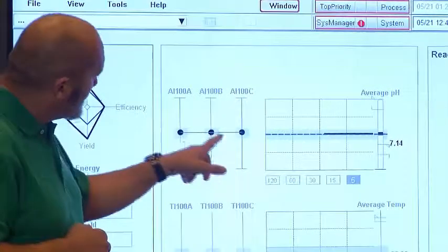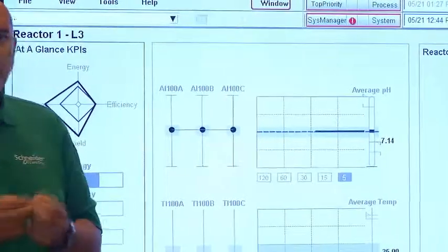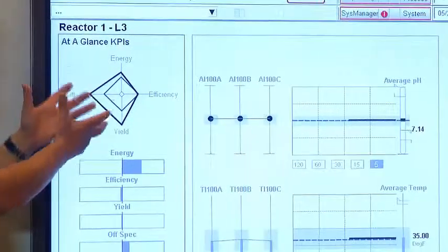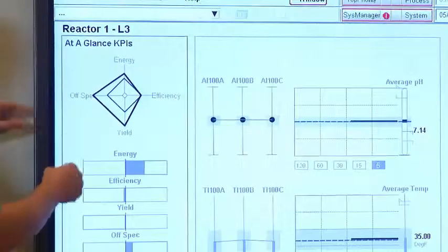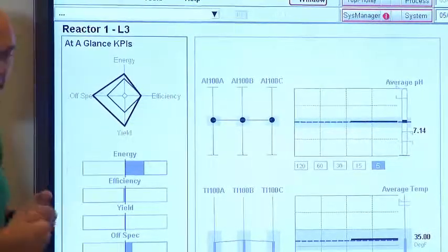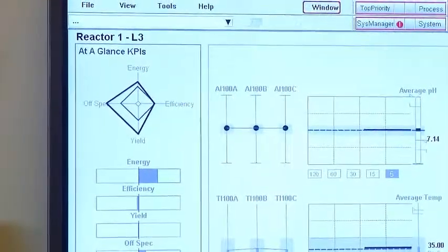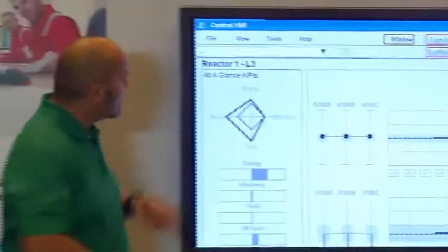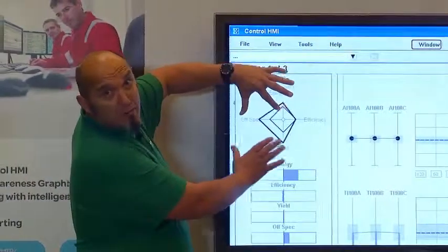We can take this concept even further. Rather than just showing them lines of process variables that are linked together, we can represent these symbols as a polygon, as an animated polygon. So we have 4 distinctly separate variables. When those variables have the most optimal relationship to one another, they will form a regular polygon.